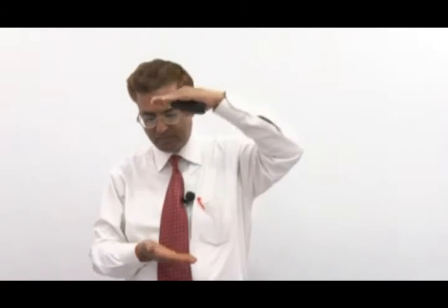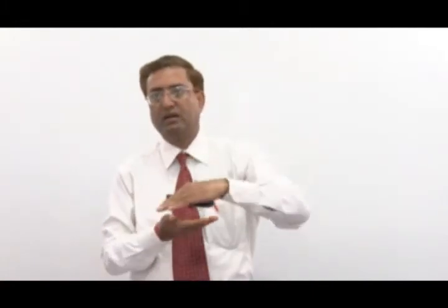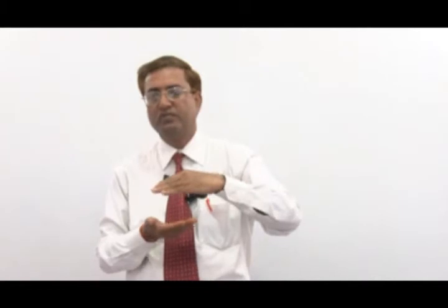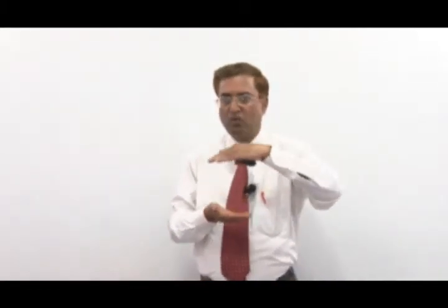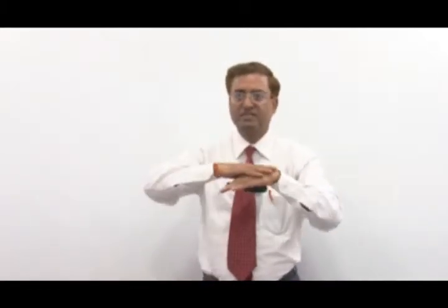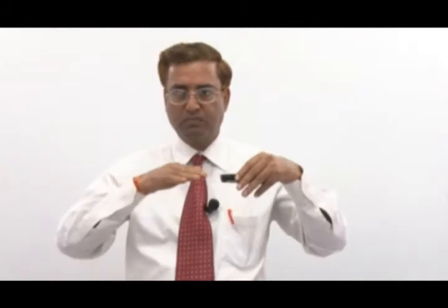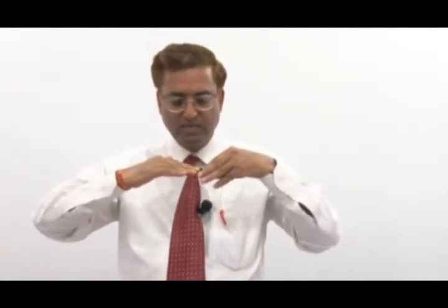Because there is a compressive stress, let me call it sigma y, acting at the two interfaces, the upper die and the lower die. If mu is the coefficient of friction, then the frictional stress is mu sigma y. The material is going to flow in the x direction.